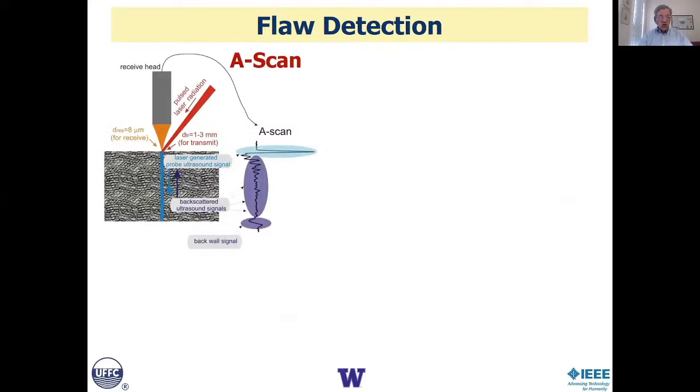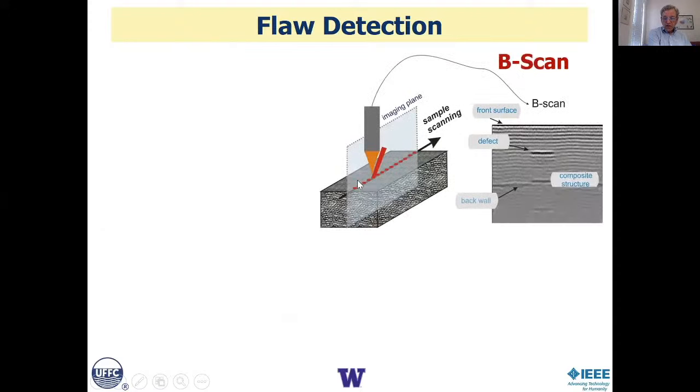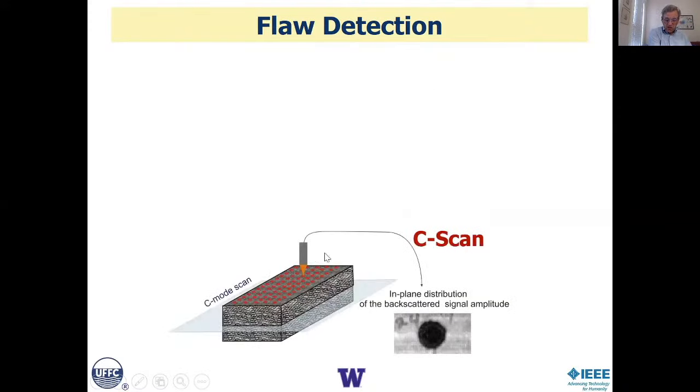And the approach is, so just so you can understand some of the images, the A-scan, like in traditional ultrasound, which is a pitch catch, and you just look at reflected echoes with depth, so time is depth, and so you get one dimension profile of reflections from the object. If you now scan source and detector simultaneously together along a line, you can get vertical cross-sections, which are B-scans. If you sweep out those source and detector in a 2D grid along the surface, you can get three-dimensional images, which is what we do.